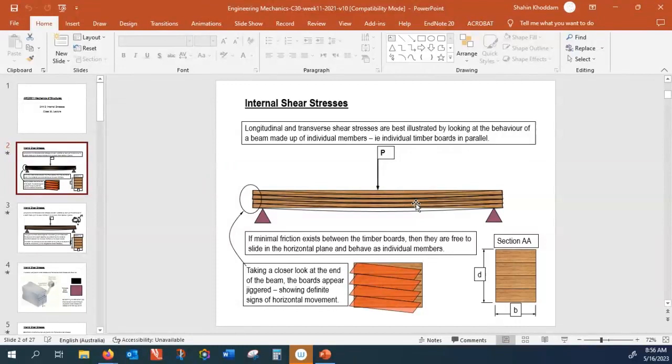Also, the very same thing can be justified at the bottom. Bottom is the last layer. So when you bring an imaginary layer after that, there is zero. So you could think that this is not quite the same as normal stress due to bending. Because when I bend, the maximum normal stress develops either at the top or at the bottom, depending on which one is farther from the neutral plane. But here, you expect the maximum to be somewhere right in the middle.